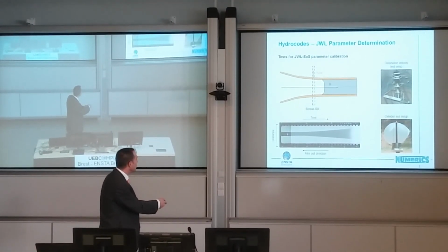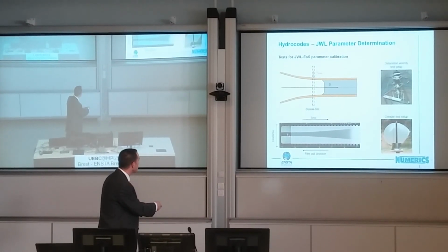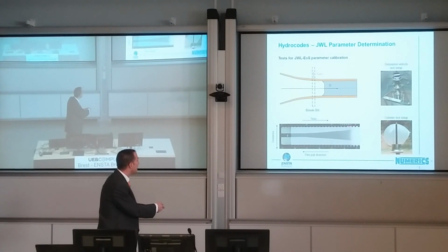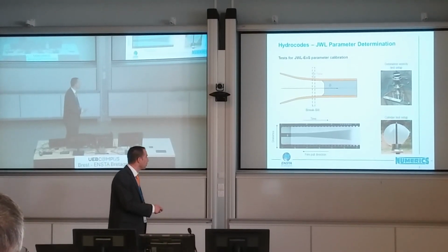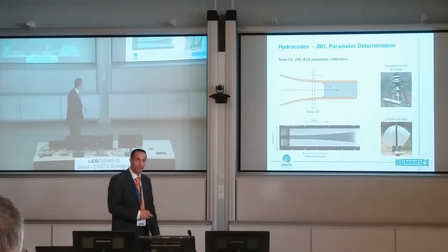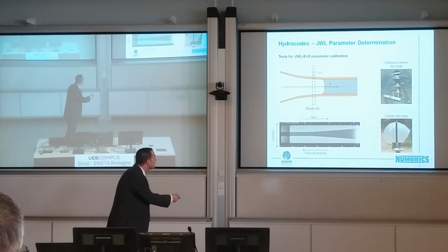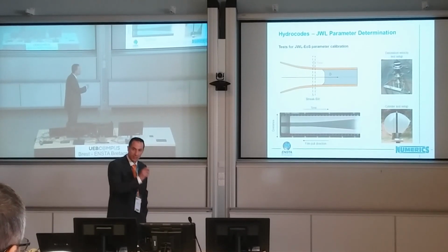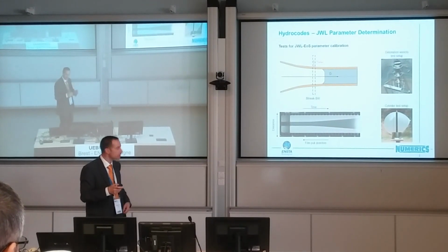So this is the time direction and this is the film pull direction. And here we see the distance. We have the initial distance of our cylinder, and with time it expands. You can evaluate this with a ruler, but we prefer a more precise method with another in-house software with edge detection and images. We determine actually this slope here. We have some marks of the distances so we can exactly know the dimensions, and we have some scaling points.